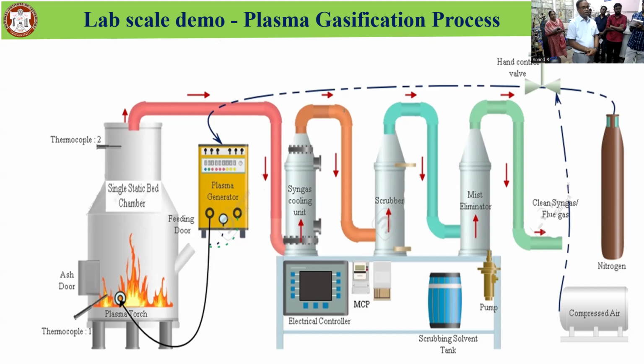In gasification mode, the products come out in solid, liquid, and gaseous forms. In general, there are only two products: solid and gas. The condensable gas we can call a liquid. The non-condensable gas is a synthetic gas, along with carbon dioxide and traces of other gases, which comes out of the gasifier system and can be used either for producing heat, or in an engine for producing power.